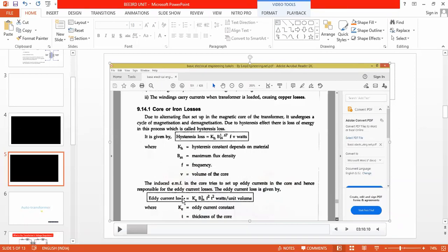Repeatedly asked in the examination, what is the definition of eddy current loss? So I've gone beyond the textbook range. I brought you that particular explanation. So you have to remember the mathematical formula. What people mention to us is eddy current loss is given by certain constant into f square, frequency square, and thickness of the material square, and magnetic field intensity square. So you should remember this formula after writing that explanation. Anyone, what is the definition of eddy current loss?